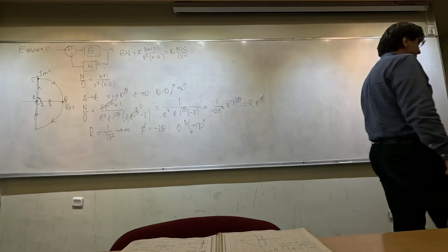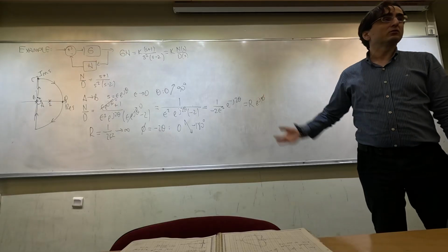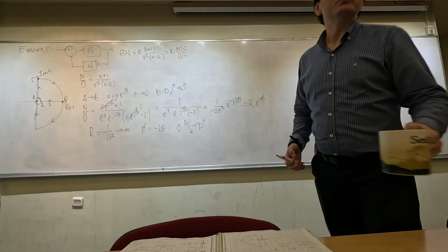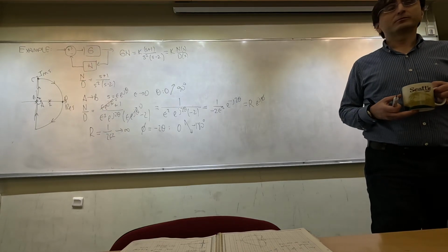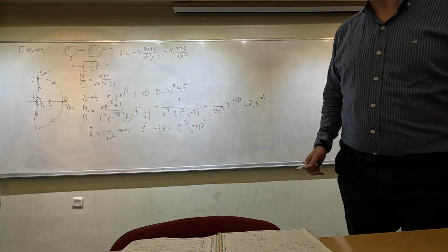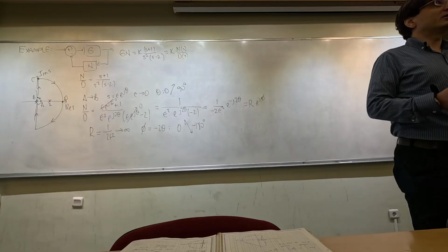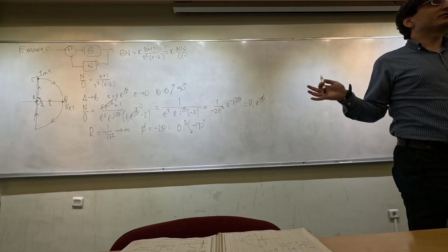Okay? What is wrong? Something is wrong there. This is not going to be the Nyquist plot. Yes, the problem is at minus 2. What happens there? What is the problem there? Is that associated with the phase? Yes. Yes, that minus 1 there has a phase itself. Okay? It's 180 degree phase, and I'm neglecting it completely in this type of analysis.